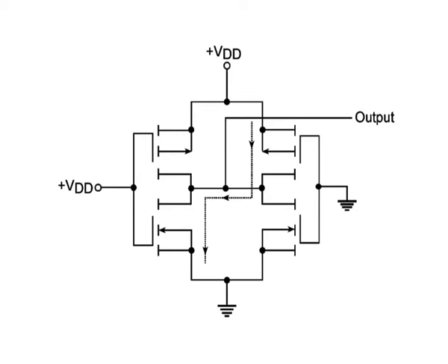equal to the on resistance of a conducting MOSFET. The output is then approximately equal to VDD by 2, which lies in the intermediate range and is therefore unacceptable. Also, an arrangement like this draws excessive current and could lead to device damage. This problem does not exist in CMOS gates with open drain outputs. Such a device is the counterpart to gates with open collector outputs in the TTL family.